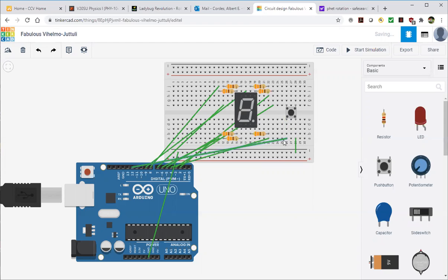It actually makes use of what's called an internal pull-up resistor on the Arduino. So what that means is that you don't have to bother using an additional resistor when you wire up this switch. So when you're ready to wire up, you can see exactly. It's very easy. Just one side goes to port 12 and the other side goes to ground.